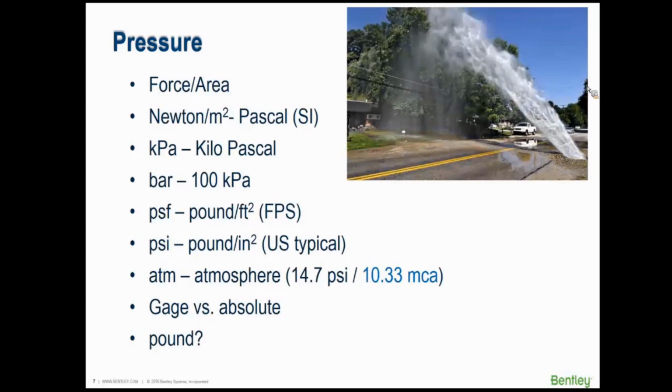So this is the force that the water exerts on the pipe. It's pushing out, trying to break the pipe. Okay, so if I ask you now, what's the correct unit for pressure? The correct unit for pressure is the Pascal, which is a Newton per square meter. But if we did a show of hands in the class, probably no one uses the Pascal. And the reason we don't usually use it is the opposite of the reason we don't use cubic meters per second. A Pascal is a very tiny amount of pressure.